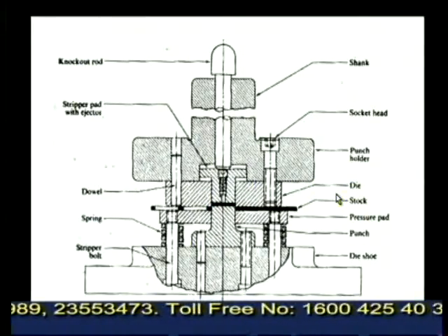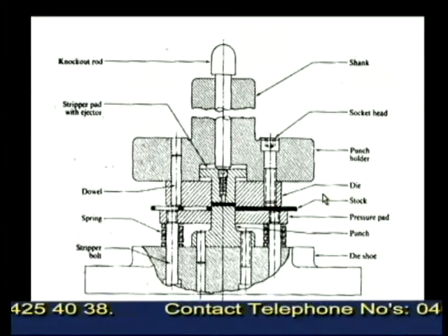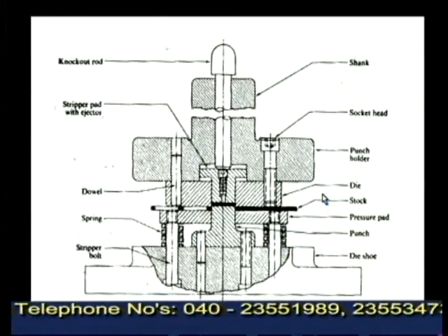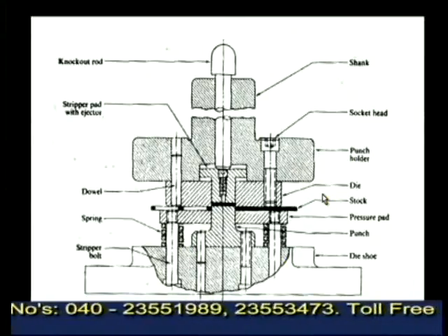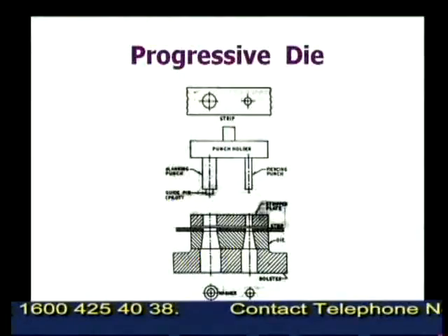And of course, the same blanking operation can be done by using this inverted die also. The advantage of inverted die is that even if the thickness of the stock material or the blank cut is thin, it will not be deflected and the blank is perfect.